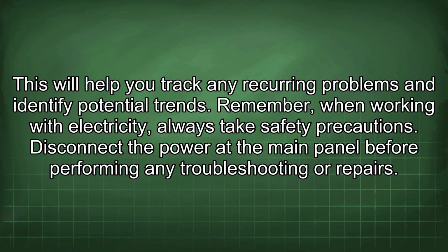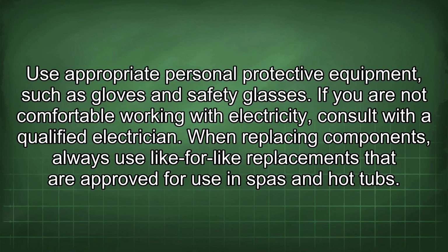Remember, when working with electricity, always take safety precautions. Disconnect the power at the main panel before performing any troubleshooting or repairs. Use appropriate personal protective equipment, such as gloves and safety glasses. If you are not comfortable working with electricity, consult with a qualified electrician.